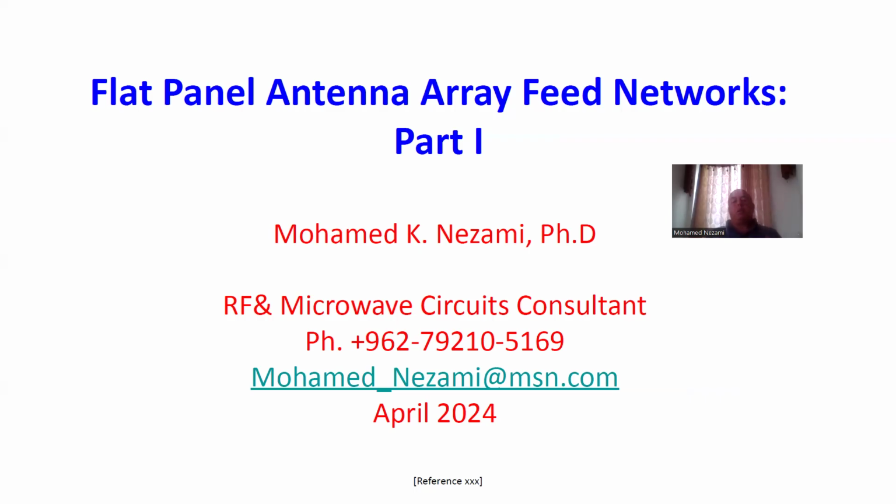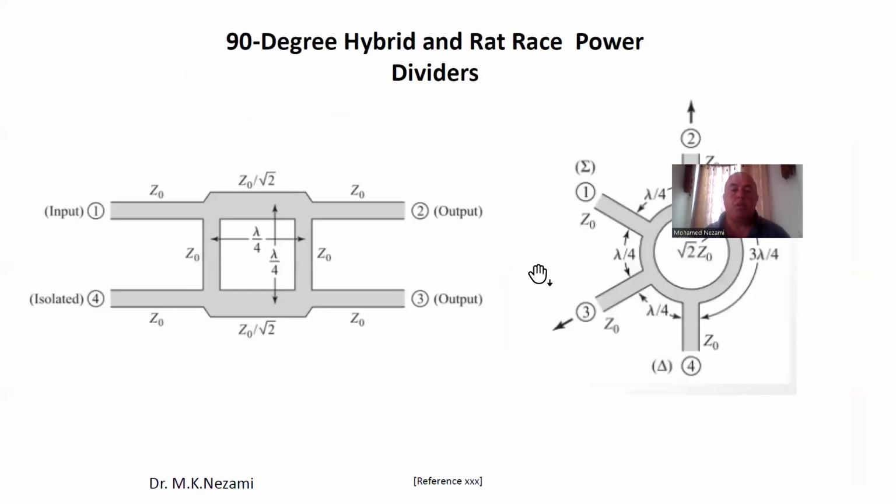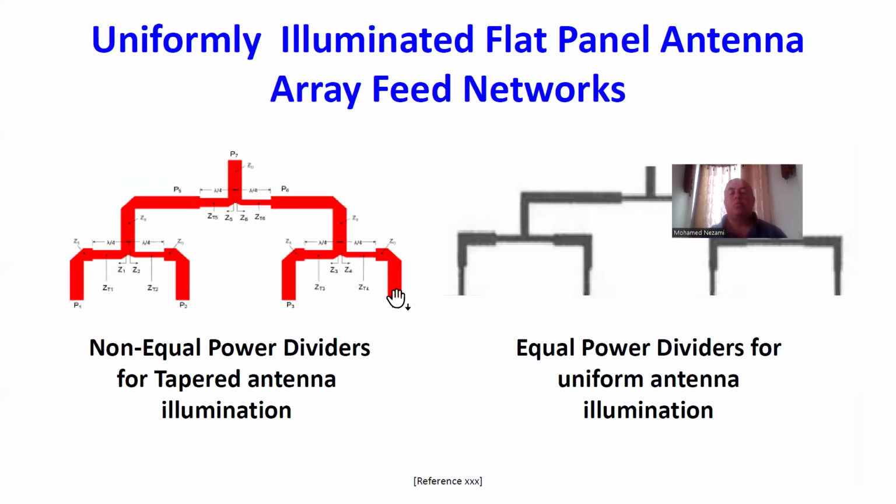So once we do all of these, we can take this to HFSS. We can take the image of these dividers in here. Once we design the entire feed, you could export it from ADS into HFSS if somebody already has the aperture design, the array, implemented in there, because most people do antenna aperture designs in HFSS. Or you could build it manually in HFSS. But at least ADS gives you the quick way of rapidly modeling this and verifying the intended design.